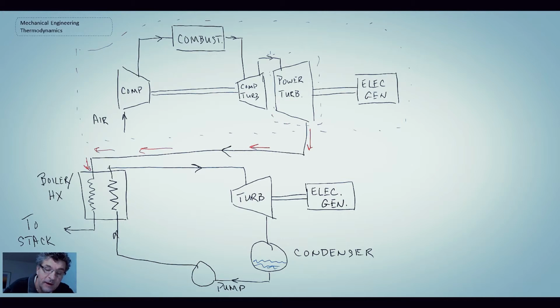That generates steam. And then that steam flows through a normal Rankine into a turbine. We get more electricity generation, and then we have that cycle there. So that's why we would call this the topping cycle, because it's at the top. And this would be the bottom cycle because it's at a lower temperature in terms of the temperature of the exhaust gas coming out.